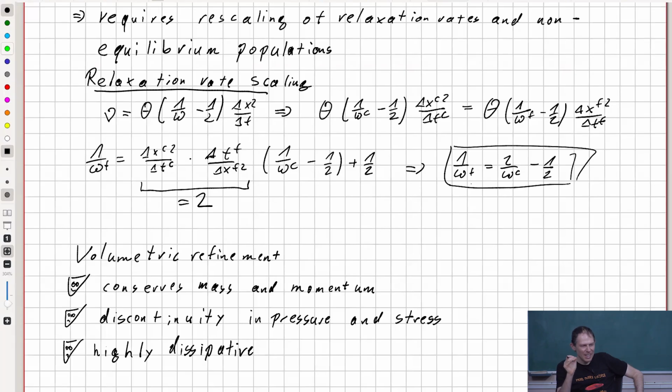And then saying that your method is dissipative, the mathematician would potentially say that this makes it inaccurate, right? But if it's dissipative, it is stable. And this is of course a big problem if you are in the late 20th century and you want to simulate the turbulent flow of a car at Reynolds number 6 million, right? You have a stable method, you get a result. That's very important. So if this is good or bad, you decide.